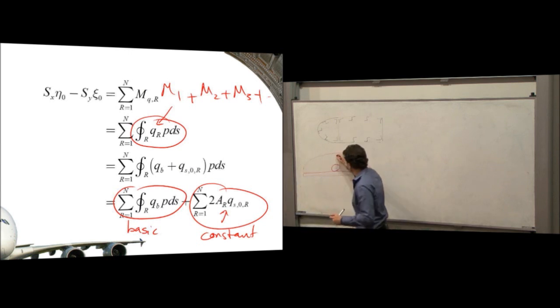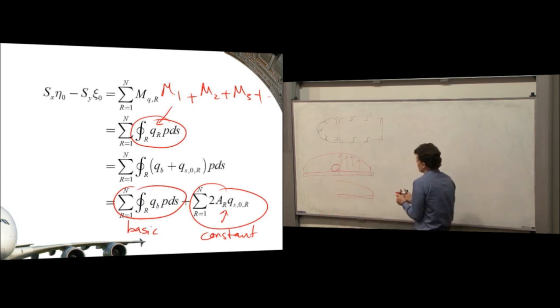Once I know my lift, I can work out what my shear force and bending moment diagrams look like. So at any point you can work out what the shear force and the bending moment is in the wing.